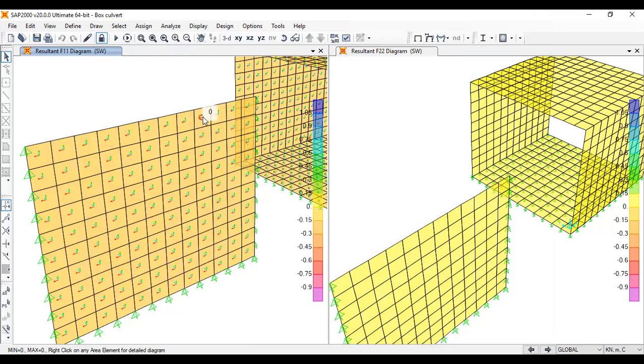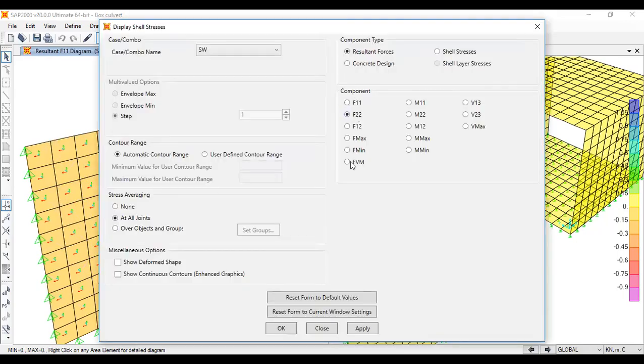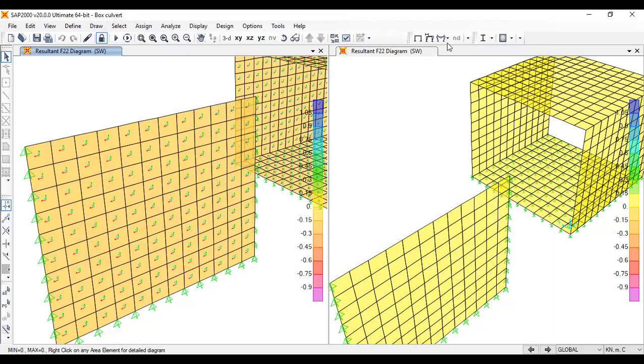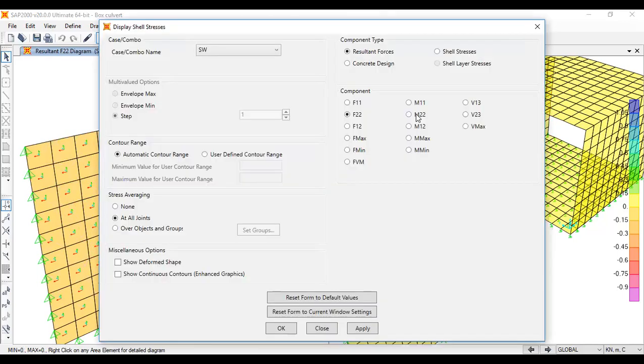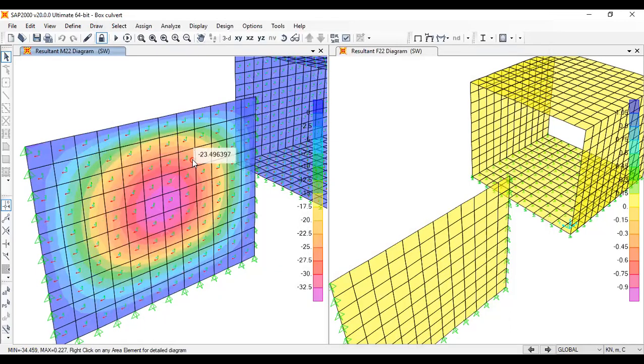It can't take them, so it's zero. No membrane forces, but it has out of plane bending, right? So for a membrane, you had only membrane forces, and out of plane moments are zero. And for a plate, your bending values are there, but membrane forces are zero. In a shell, both are there, right?